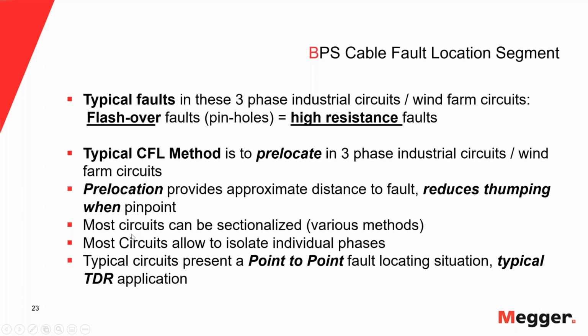So most circuits can be sectionalized by various methods. Many of these circuits have fault indicators installed, so we already have a pretty good idea where to look. But we can also, and I think Marshall eventually will talk about sectionalizing methods in URD loops, use that same technique in some of these circuits.